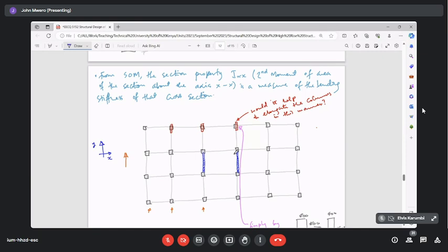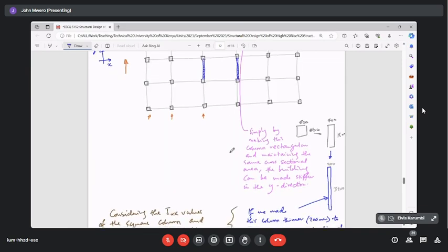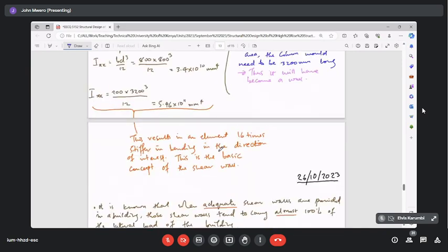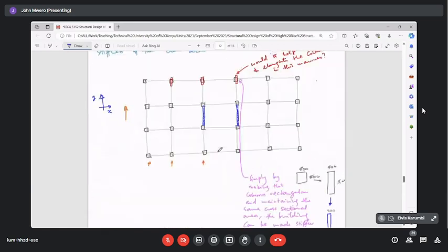If you're interested, you can check this up. It's some bit of calculation, so it might not be very juicy, but there might be a few students who might be interested in this subject. You could actually dig up the works by these fellows and see how that distribution is done. But generally, if you carry out those calculations, you find that the shear walls, like these two shear walls that we put here on this hypothetical building, will basically carry almost everything.